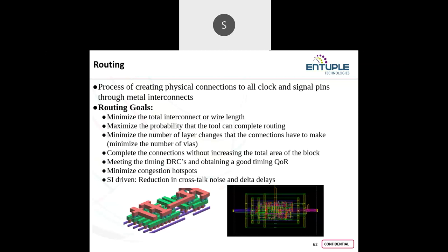If any congestions remain after fixing from the placement stage, still if I am getting any congestions after the routing stage, that congestion will also be taken care of. Once after fixing these things, whatever quality of routing database or routing results I get will be a proper one.